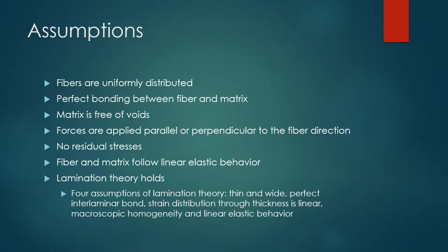We made a few base assumptions to start to simplify things in our project. First, the fibers are uniformly distributed throughout the laminate. Perfect bonding between fiber and matrix exists. The matrix is free of voids. Forces are applied parallel or perpendicular to the fiber direction. There are no residual stresses. The fiber and matrix follow linear elastic behavior, and lamination theory holds.